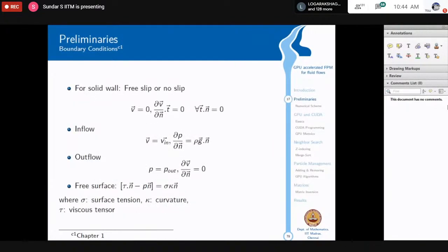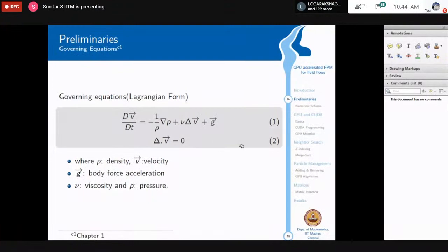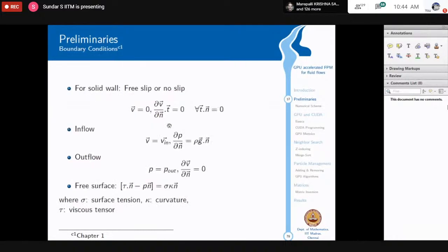Chorin is one of the famous names in fluid dynamics. I think many of you know his book, A Mathematical Introduction to Fluid Mechanics. So his method, Chorin's projection, is used for the numerical simulation. In dV by dt with V star, I am doing only these two parts. Once I know V star, I use V star to get Vn plus 1 using this gradient. By then I know my P. So that's my idea.